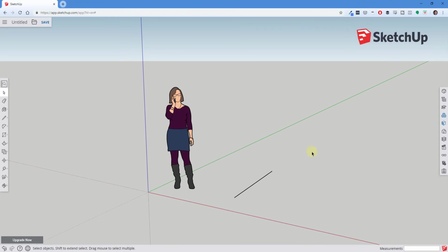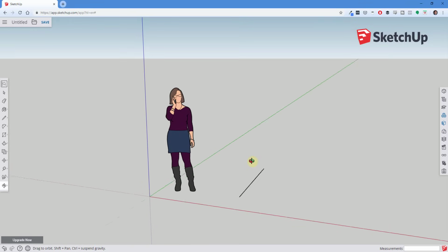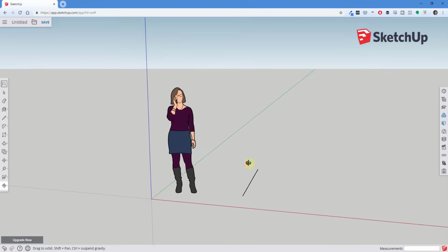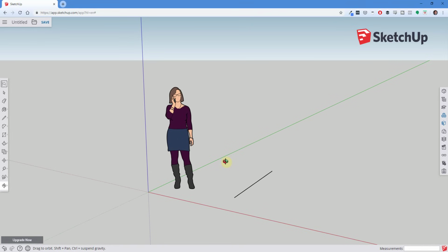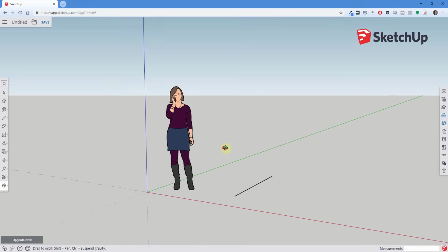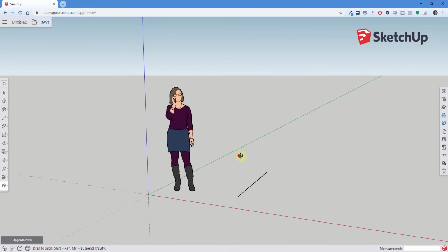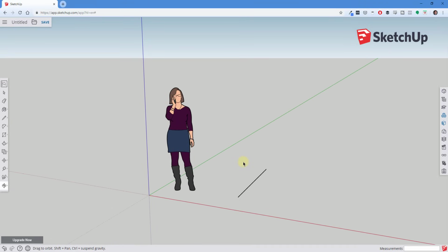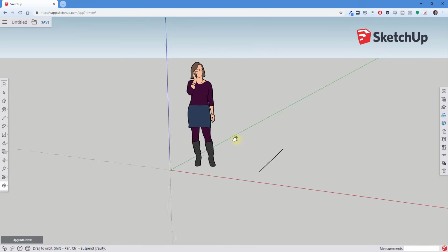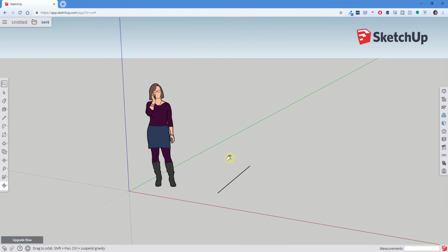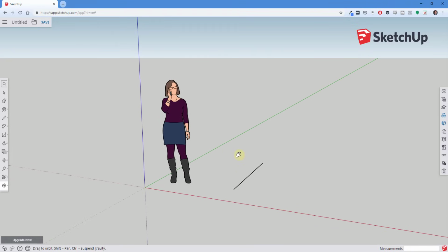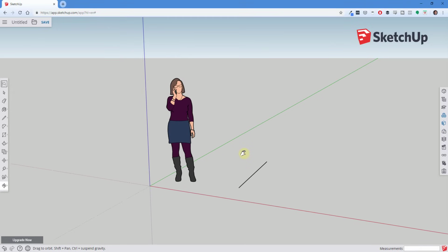And the better way to do that is if you have a 3-button mouse with a scroll wheel, which is going to be really important if you're going to be using SketchUp a lot. You're really going to want to have that 3-button mouse. What you can do instead is you can click and hold your center mouse button in order to orbit. And so what I'm doing is I'm clicking and holding that scroll wheel down. So I'm clicking it like a button, not rolling it, and holding that. So that allows me to orbit. And then in addition, if I click and hold that button down and I hold the shift key on my keyboard and move my mouse, you can see how this allows me to pan my view around really easily. So by holding that center mouse button and holding the shift key around, you can pan.